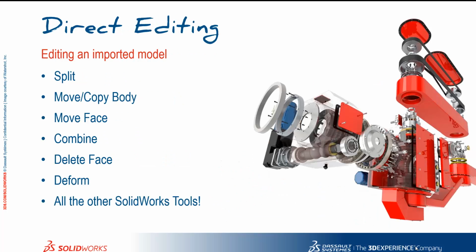So if you've been given an imported model, what we can do with it, and some of the things we're going to cover: split, move copy, move face, combine, delete, deform. And I just wanted to make the point that once you've got a solid, even if you don't know how that solid was made, all the other SolidWorks tools still work. So without further ado, let's get into SolidWorks.